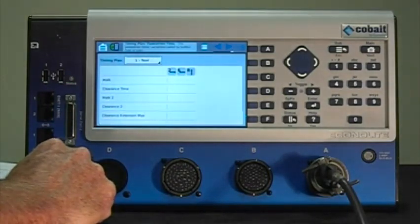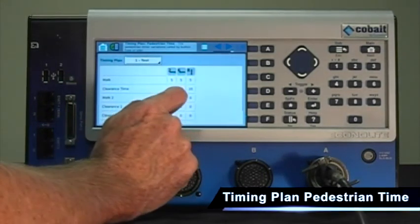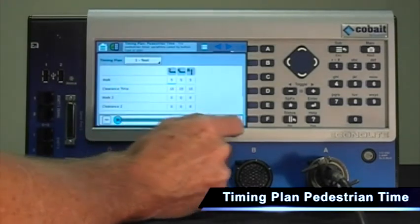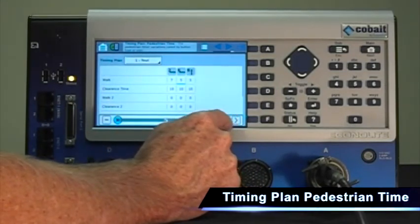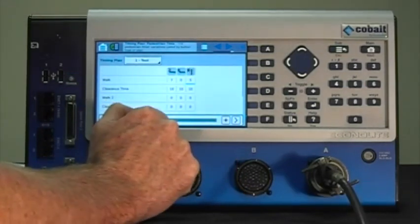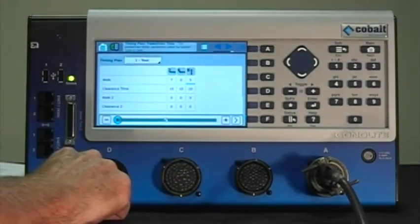And on to the next screen, the pedestrian times for walk. Let's make the phase 2 7 seconds. Remember, there is no ped on phase 6, so we'll make that 0. And then for ped 8, let's make that 5 seconds. Well, it's already 5 seconds, so let's leave that.